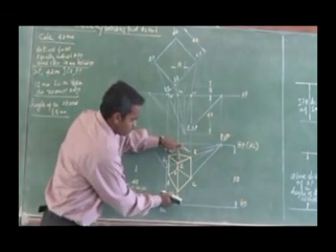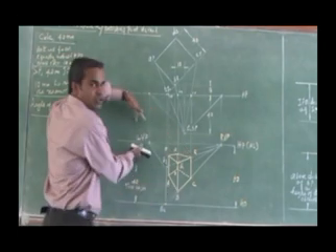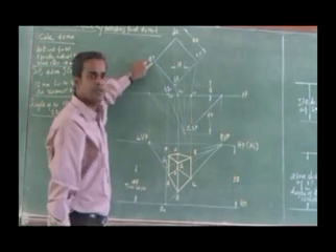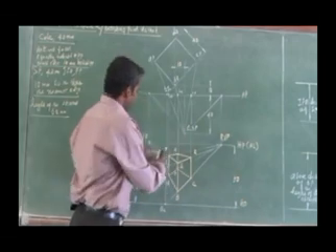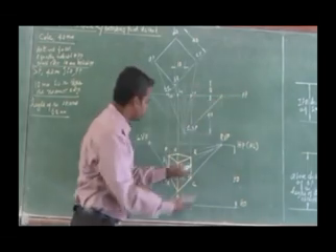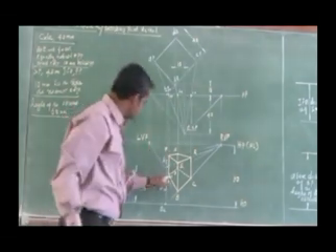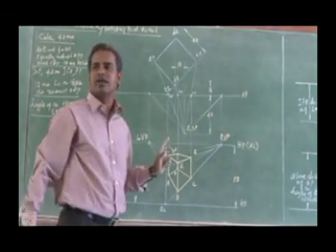The face perspective edge of BQ, that should be joined to the left vanishing point to obtain the perspective of AB. Then the corner S, by joining B to right vanishing point or to left vanishing point, the intersection will give me S. Similarly, A to right, C to left, the intersection will give me T.